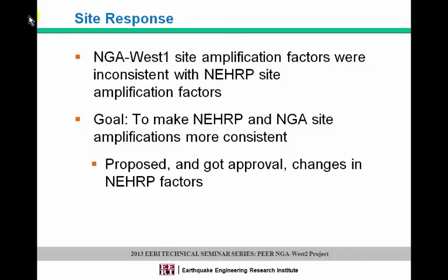We know for a fact that the ground motion prediction equations' amplification terms, soil amplification terms, are not 100% consistent with the NEHRP factors in the building code. So really it's like apples and oranges.